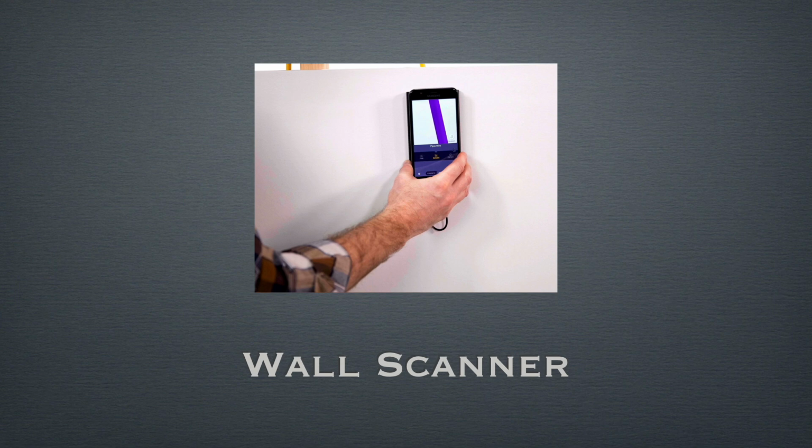If we have X-ray equipment, then it is the best solution to verify what is the reason for the alarm. But sometimes we do not have X-ray equipment, and we can use the wall scanner to check the possible source of the alarm, and checking if there are wires, for example, tubes or rusty studs or stuff like this, and also maybe objects that might appear blurry on the wall scanner, but can lead us to a decision of further investigations.